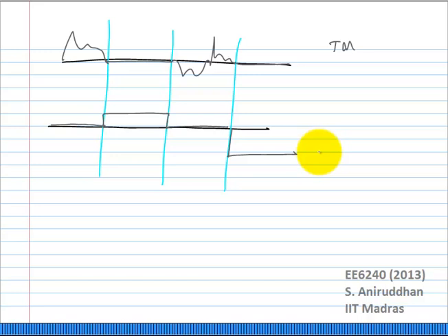Now the important thing to remember is that unlike your conversion gain and input impedance, you can't just separate these two completely. Let us say this was VN1 and VN2. You can't just add the two at the output. The reason is, most probably there is going to be some correlation between VN1 and VN2. They are going to be partially correlated.